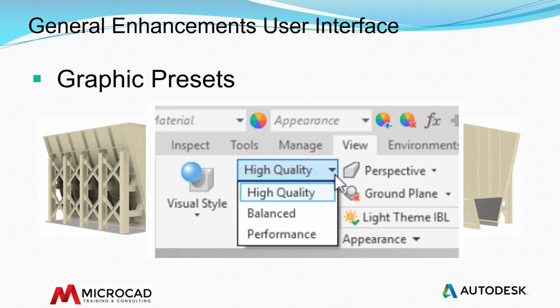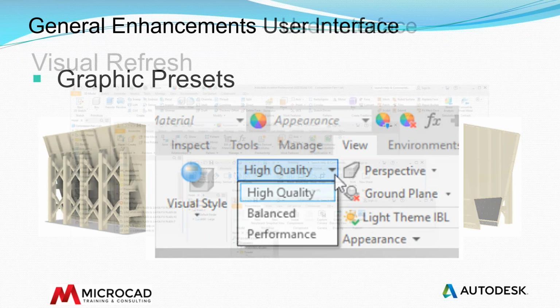Performance places an emphasis on performance over visual display. Performance is the default setting for built-in assembly templates, utilizing the new lighting style Light Theme, shaded visual styles, and no shadows, and is best for working with medium to very large assemblies.